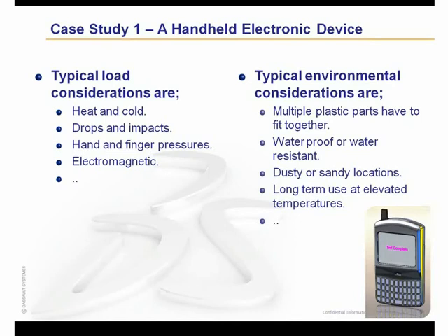Does it have to be waterproof, water resistant? Dust in sandy locations, we want to make sure that the dust and sand doesn't get into the product. Is it going to be used for a long time at elevated temperatures? Typically, electronic components don't like that kind of behavior.